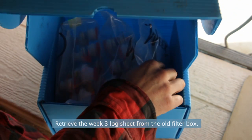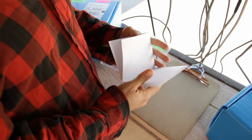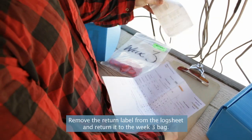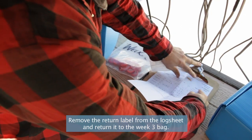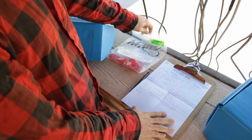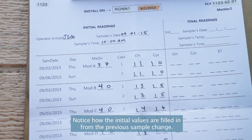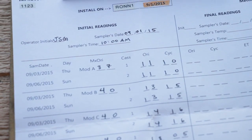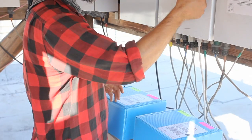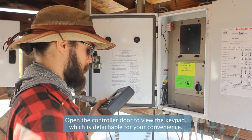Retrieve the week 3 log sheet from the old filter box. Remove the return label from the log sheet and return it to the week 3 bag. Notice how the initial values are filled in from the previous sample change. Open the controller door to view the keypad, which is detachable for your convenience.